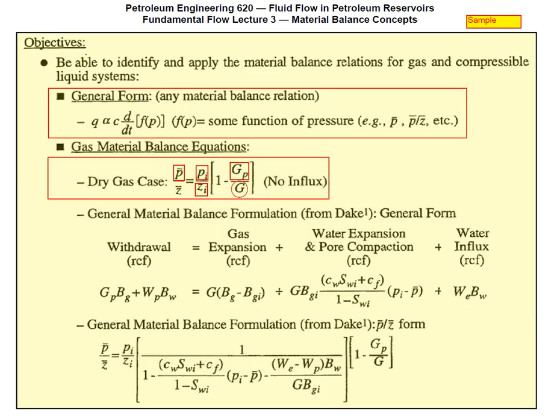What would your manager say, Santiago, if you wanted to shut in a well for a year? What would he say if you wanted to shut it in for 6 months? Three months. 1 month. 1 week. Right. That's why in the literature you always see a 3-day buildup.